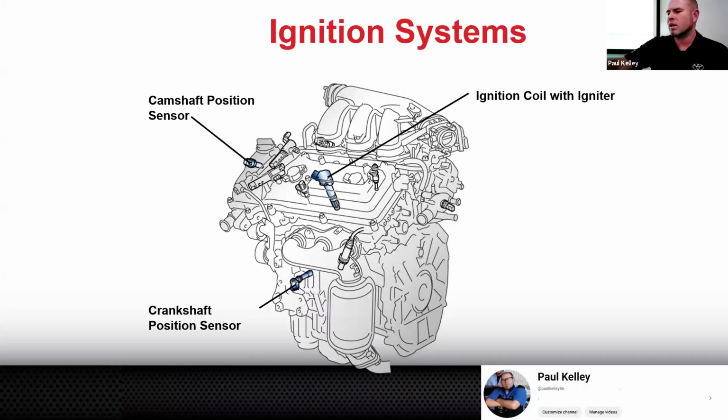I just said, it's up to you. I mean, I could give you the advice, but it's up to you to take it or not. You could call the mobile mechanic back, and he'll come back out and replace some stuff. And then she's kind of like, no, no, I don't want to do that. Why don't you tell me what you think? And I just said, the primary circuit is the small wires going to the coil. You need to find out if there's an open between your ECM and the coil. And where we live, mice probably chewed that. Right off the hip, I'm going to bet you, a mouse chewed the primary side of the circuit.